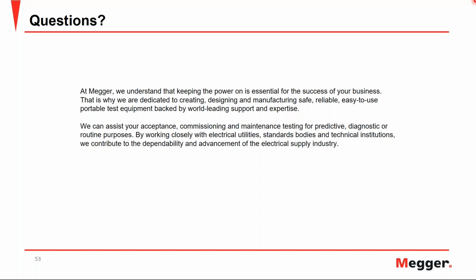Power factor, as shown with the permittivity equation, is dependent on frequency and temperature. Traditionally we have always done the test at the same frequency, so we were not used to seeing the dependence on frequency. We were just seeing the dependence on temperature, because depending on when we are testing, we will always have a different temperature on the transformer. So they are not the same at different frequencies, and that is very important to consider when reviewing the results.